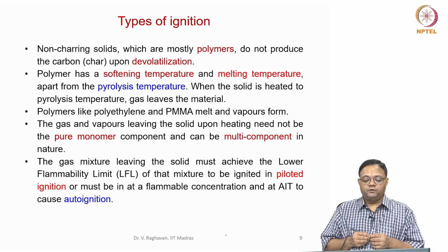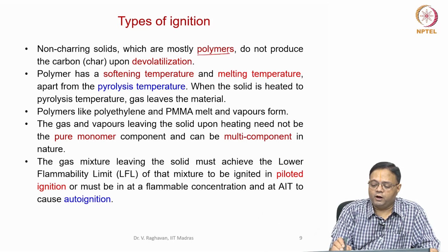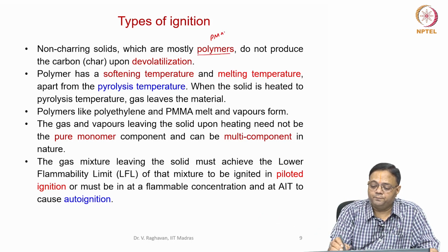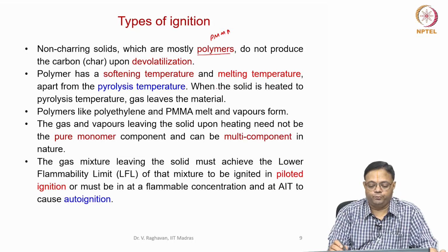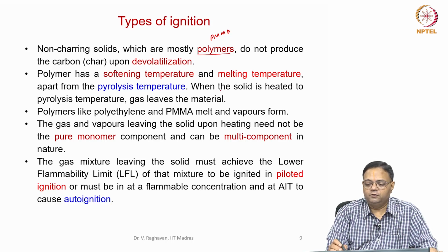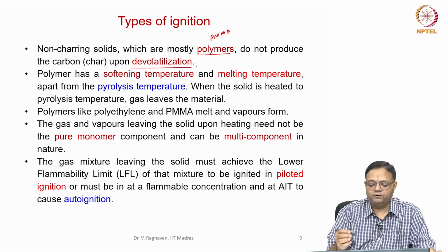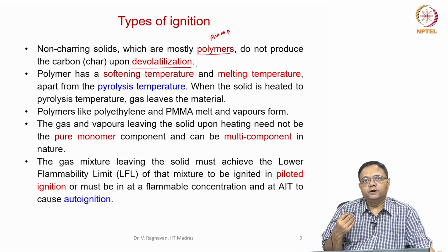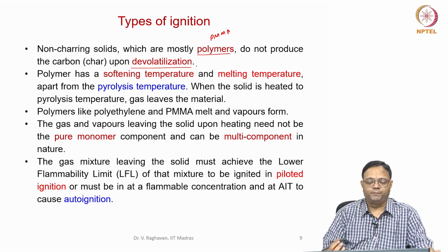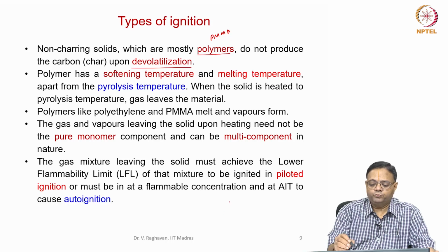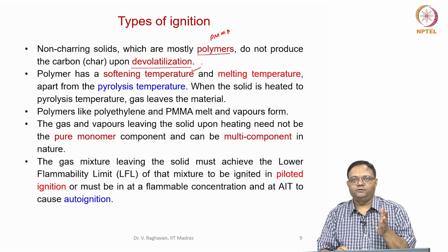Going to the polymers or non-charring type of solids, where polymers are basically like PMMA or polyethylene etc., they will not produce a carbonaceous residue. It may have some impurities, but upon heating it will just devolatilize. That means it may melt or it may sublimate to produce the vapors. Now, the hot plastic can soften.